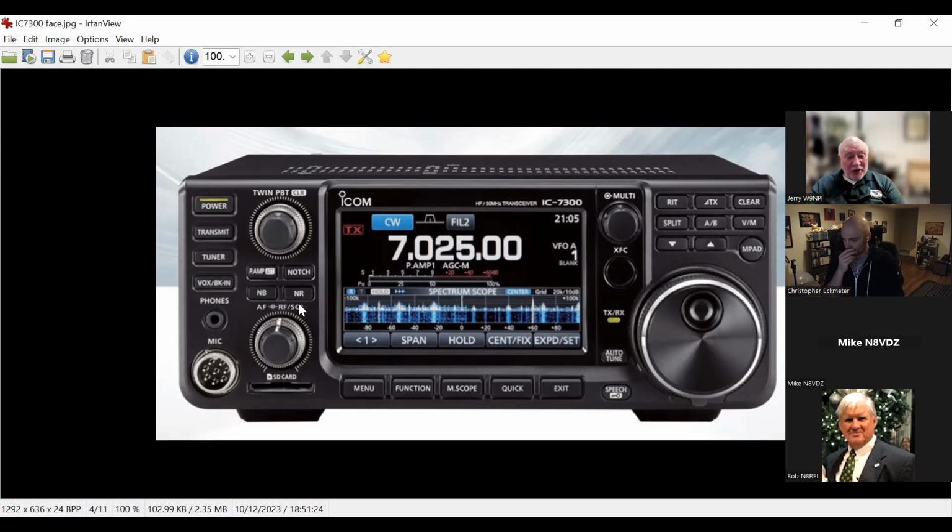It's got a squelch in there, although you don't really use it very much on HF. And it has two ways of adjusting your signal strength. One is actually increasing or decreasing the sensitivity of the radio. That's the RF section. That's the outer ring of this volume control. And the inner one is simply a volume control.